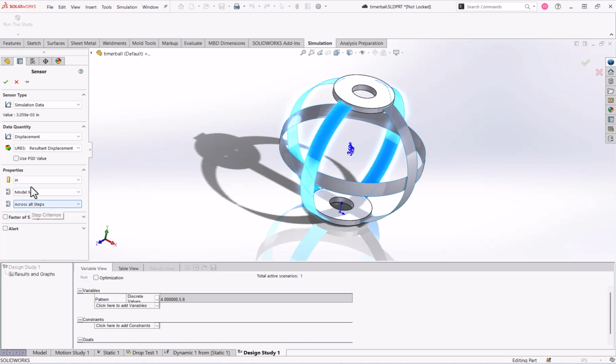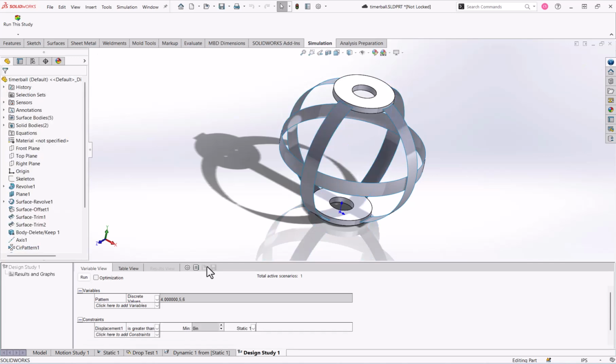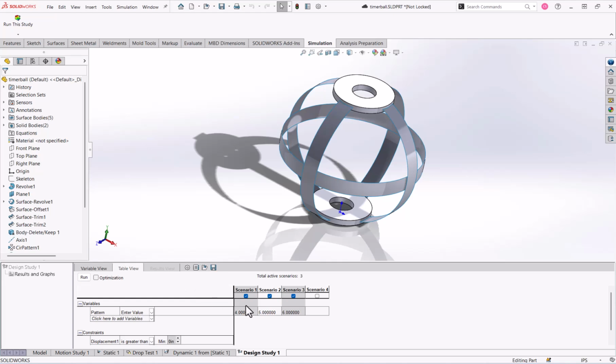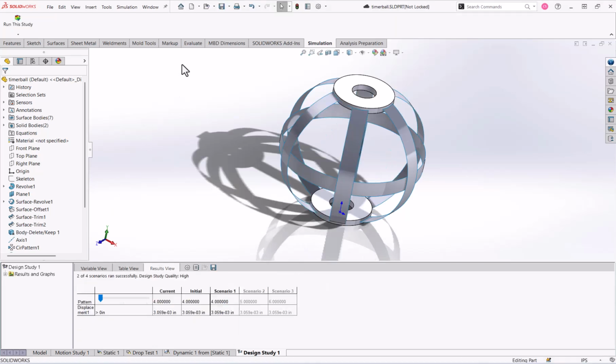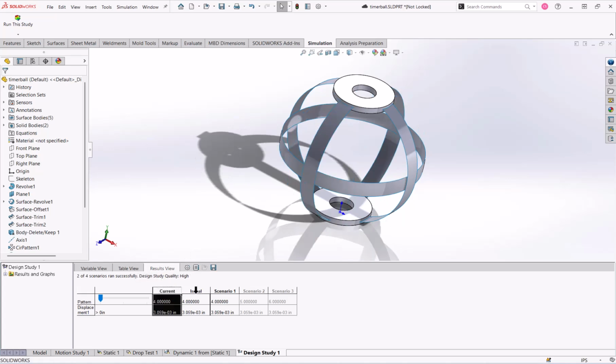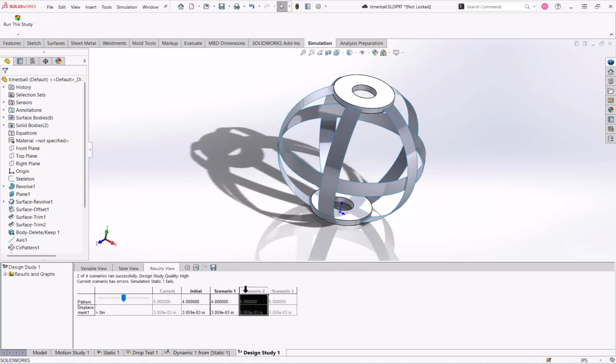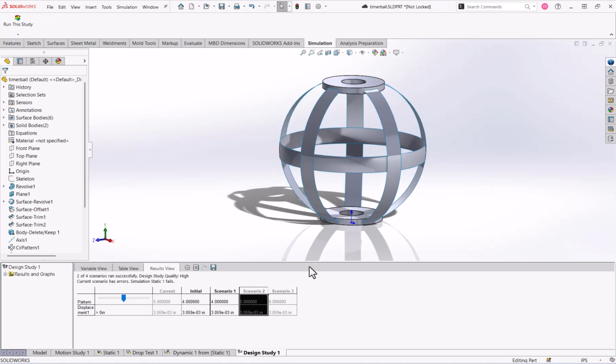And I can see if there's any change, if adding more bands makes this a more stout or more robust design. Some people might call this sensitivity analysis. And once the software is done processing our different combinations, we can interrogate it, looking at those constraints and seeing if we've improved the design, made it worse, or in this case, it had no effect under this particular loading case.